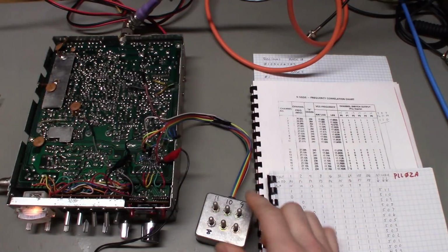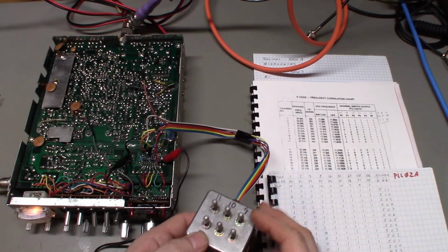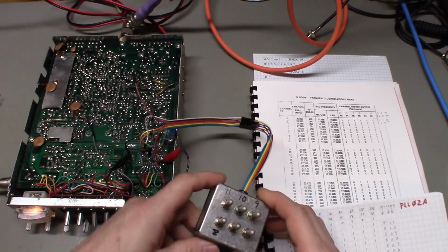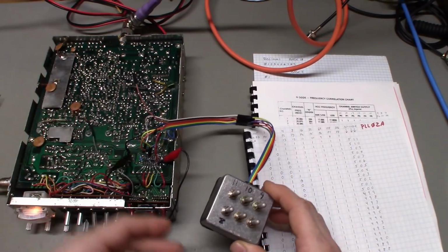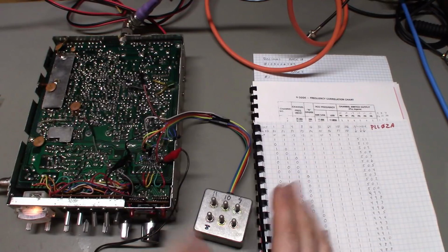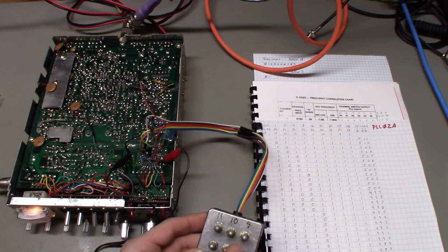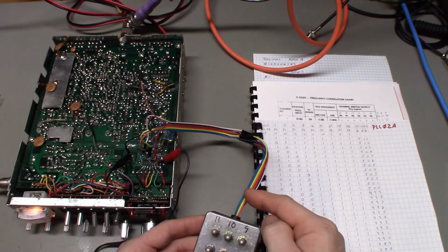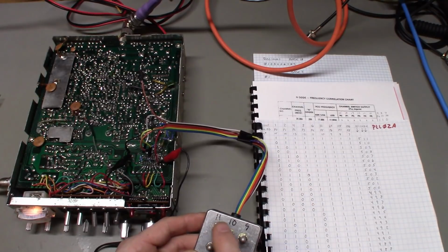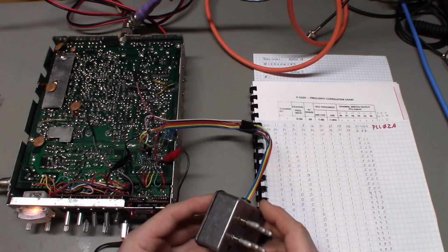Now this little box I've had for years, made this thing up a long time ago. You can make one of these up, they're handy to have. Just take a little project box, doesn't have to be a Bud aluminum box, I just like them because they're indestructible. I only have 6 switches in here, because usually that's about all you'd need to really play around with. But there's 6 switches and there's 8 wires that go in and out of this box. There's 8 wires because I have 1 wire attached to each of the center terminals on these switches. So these are 3 position switches.